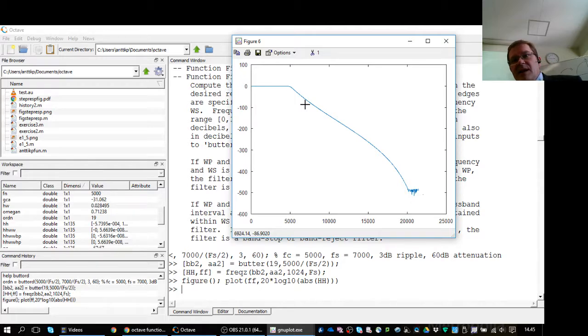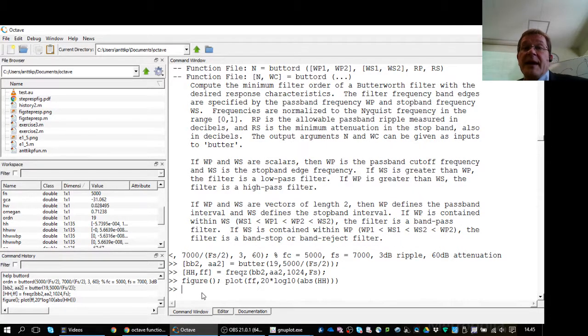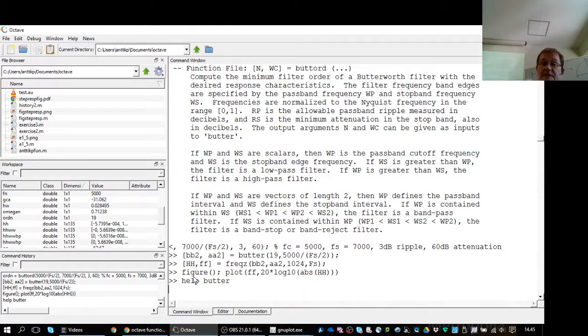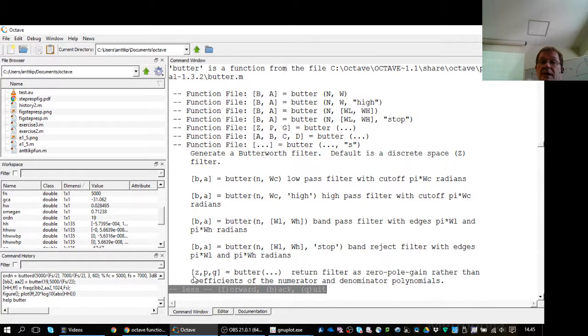How to design high-pass and band-pass? Well, quite a similar way. Just a moment. Let's take a look at the Butterworth filter design program. You can also just select that one to high-pass filter. So low-pass, high-pass, band-pass, where we have lower and higher cutoff frequencies, and band-stop. One single function gives all of those. You don't need to worry about the modulation. You can modulate though, but then you need to modulate both the numerator and denominator separately. So that's possible. It still has the same effect.